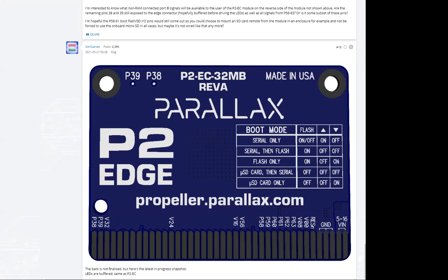The main advantage of having only 4 layers is that it made you think about not passing high frequency signals into internal layers, where they are very hard to calculate all the interferences from the layers that surround those signals.